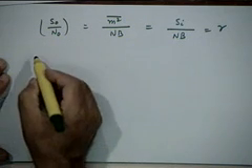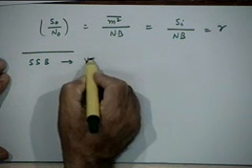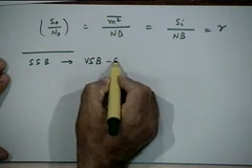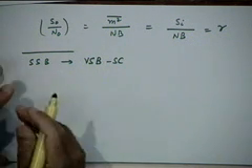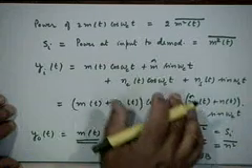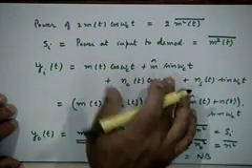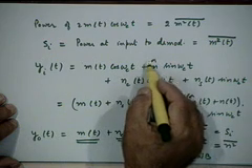Now, when you go from SSB to VSB, suppress carrier once again and carry out synchronous demodulation, using the same arguments that we have used here. If you remember, we have a very similar quadrature representation for the VSB signal, except that this is no longer the Hilbert transform.